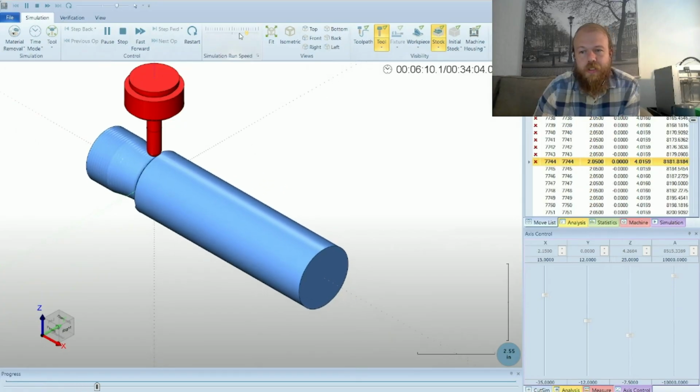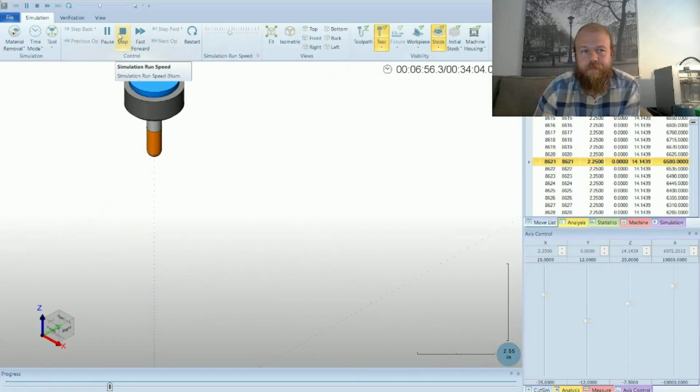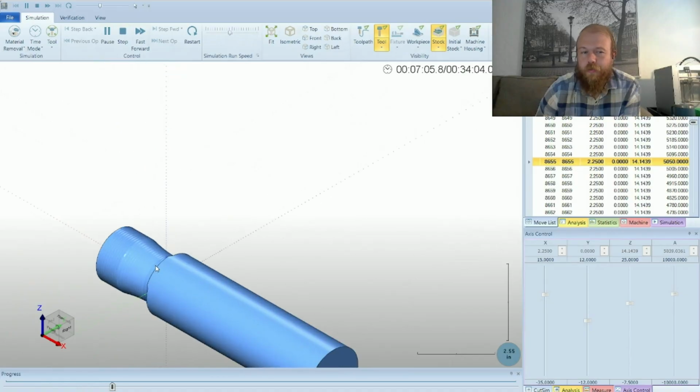And if you have an older machine that has a certain limit in your A axis, it can only revolve a certain number of times before it has to rewind to get back to its original spot. What it's doing right now is it got to A 9099. I'm sorry, 9999, because this machine specifically, we have it programmed so that the limit in the A-axis is positive and negative 10,000 degrees. So it got right up to 10,000 degrees in the A-axis.